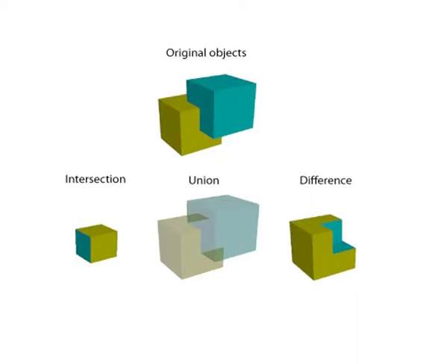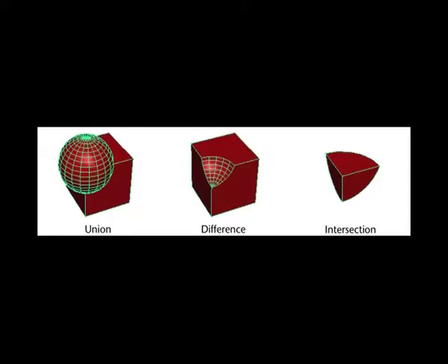Maya creates a new shape node for the compound object, deletes the shape nodes of object A and object B, but leaves the transform nodes until the history is deleted. That means you can still move both objects after the Boolean operation has been performed to change the outcome. Use the outliner to select the transform nodes. History of object A and B will become combined in object C.